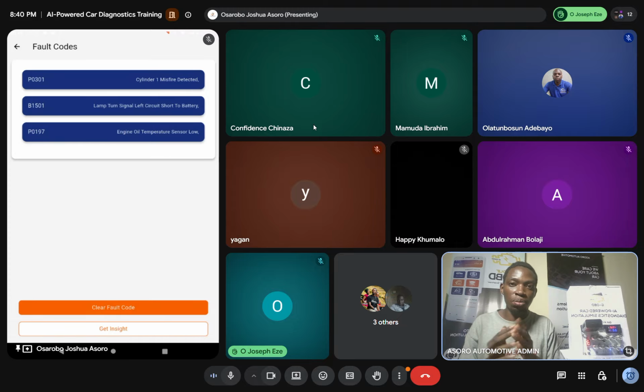We'll get back to you. Let me just explain. If you notice, most diagnostic scanners like the Autel, the Launch, those scanners that we use, we pay yearly for them, right? Why do we pay yearly for them? Because they can scan some stuff that those cheaper scanners cannot do, or they can program some stuff that those cheaper scanners cannot do. Why does that happen?